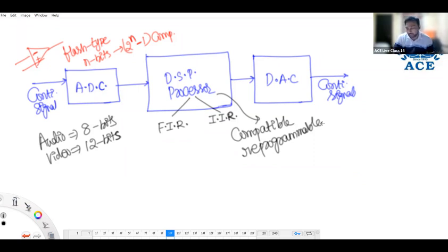In all our discussion till now, you remember two things. Continuous signal definition is, at any instant of time amplitude is defined. Only at certain instants of time amplitude is defined means discrete signal. At any instant amplitude is known means continuous. Only at certain instants amplitude is defined means that is called a discrete signal. These two things you remember.